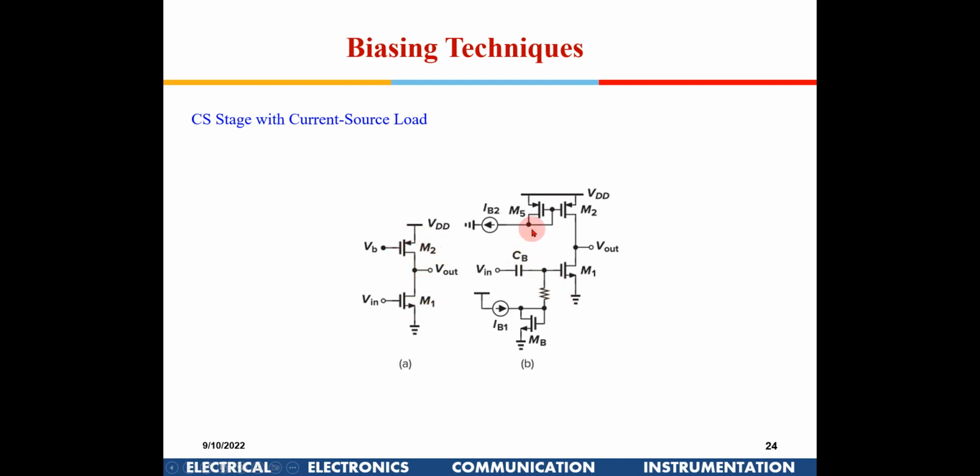Now, if I have a reference current, I can use a current mirror here like this. So this is the biasing at the gate, this is the biasing at the top. Is this circuit understood by all of you? What we have done, right? Sir, but here also that resistor will be replaced by the MOS, right? Yeah, you can replace this resistance with a MOS.